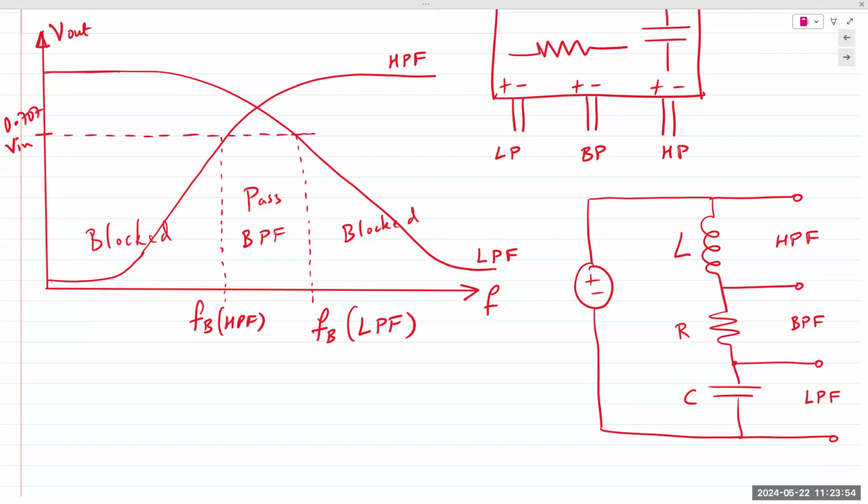So if you have an inductor and a capacitor in the same circuit, in the positive half cycle, energy flows into the inductor; in the negative half cycle, energy flows out, but it goes into the capacitor. Next positive half cycle, the energy flows out and goes into the inductor. So it bounces back and forth between the inductor and the capacitor. When a switch is first flipped on, both of them are empty. There's no energy in either one of them. Positive half cycle, the inductor fills up. Negative half cycle, the capacitor fills up. From that point on, the energy is localized, bouncing back and forth between the two like a ping pong ball